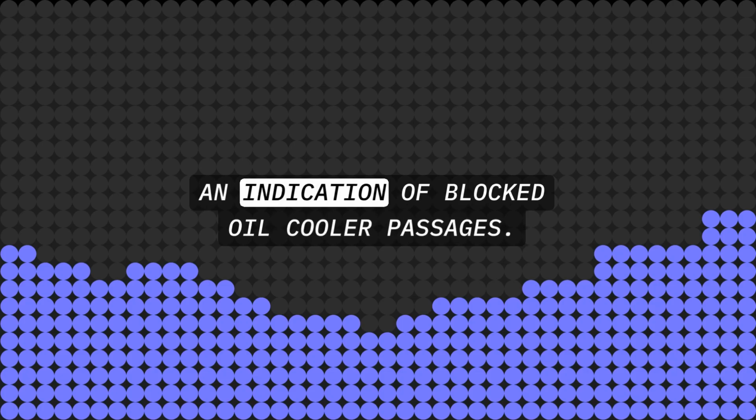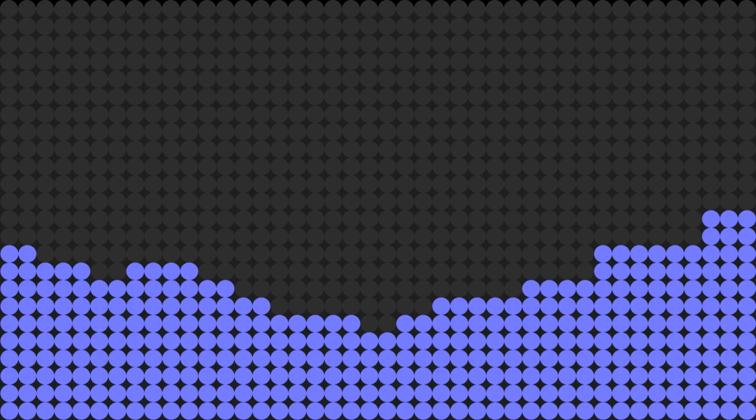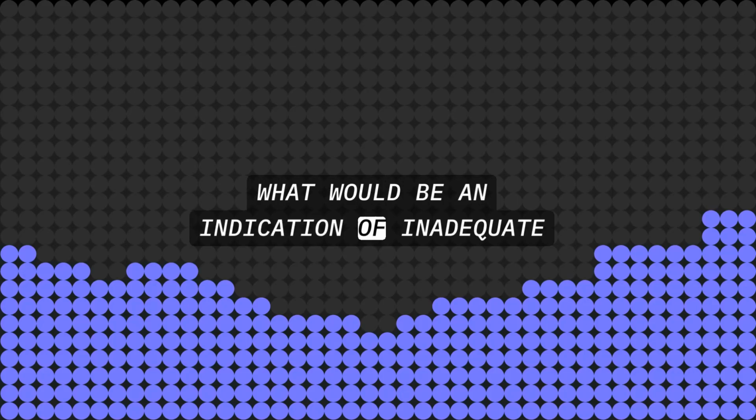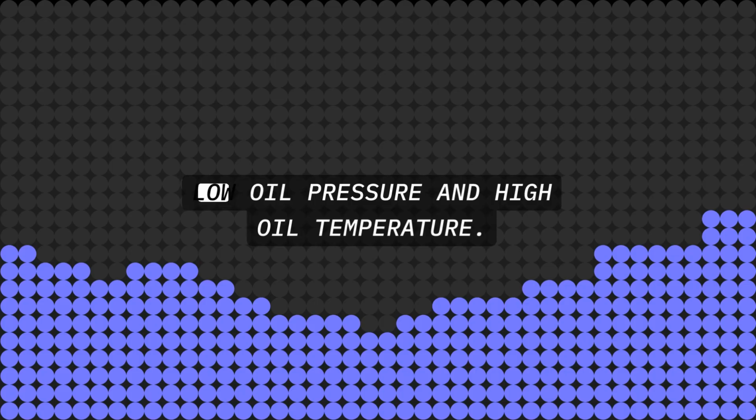What would be an indication of blocked oil cooler passages? High oil temperature. What would be an indication of inadequate oil supply? Low oil pressure and high oil temperature.